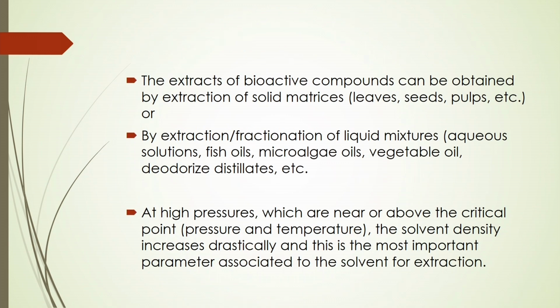The extracts of bioactive compounds can be obtained by extraction of solid matrices, such as leaves, seeds, pulps, etc., or by extraction or fractionation of liquid mixtures, such as aqueous solutions, fish oils, microalgae oils, vegetable oil, deodorized distillates, etc. Also, at high pressures we are near or above the critical point. The solvent density increases drastically at these supercritical conditions, and this is the most important parameter associated with the solvent for extraction.